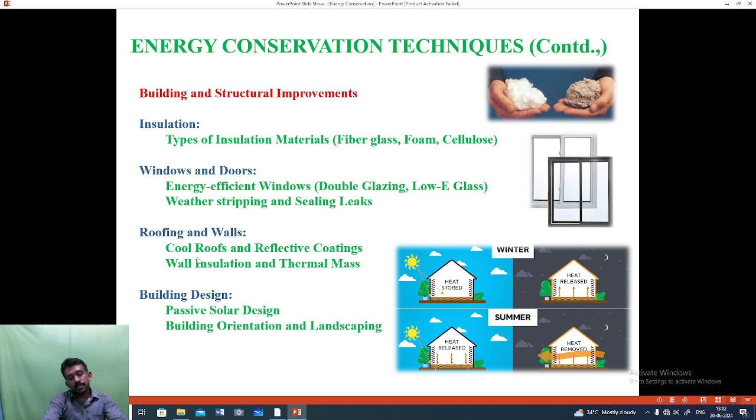So civil engineers can plan for a cool roof. The cool roof concept means we can place reflective coatings that do not absorb the radiation coming from the sun. If it is not absorbing, definitely there is a high reflection coefficient for this material, there is no heat transfer into the building, and thereby a cooler inner space in the home.